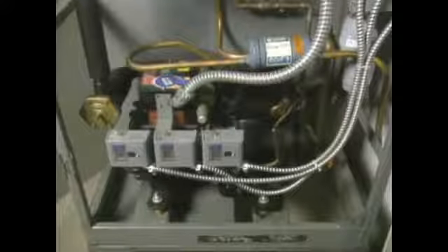When the amount of refrigerant in the system is correct, the refrigerant seen in the sight glass should be clear. If there's not enough refrigerant, the refrigerant may appear cloudy and it may contain bubbles. Another indication of too little refrigerant may be a continuously operating compressor. Some types of refrigeration systems cycle the compressor on and off to maintain the proper cooling. If this type of system has too little refrigerant, the compressor may run continuously, trying to maintain the desired amount of cooling. A similar problem is low refrigerant flow.